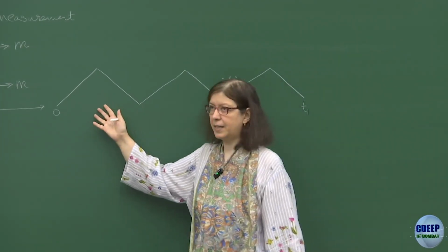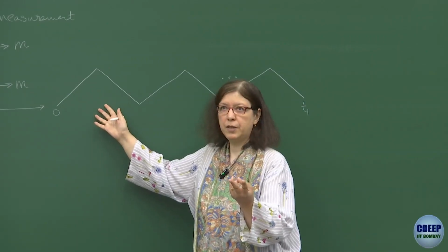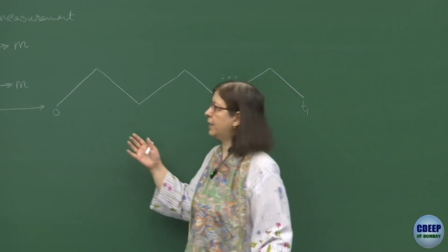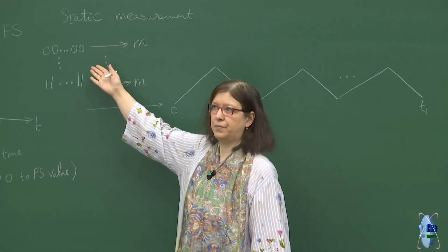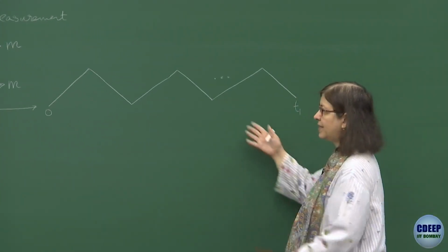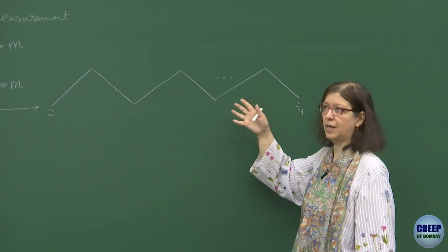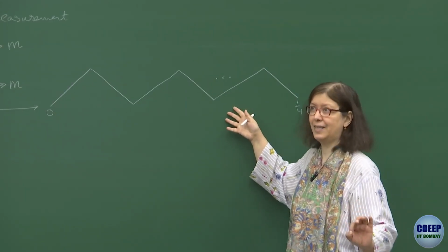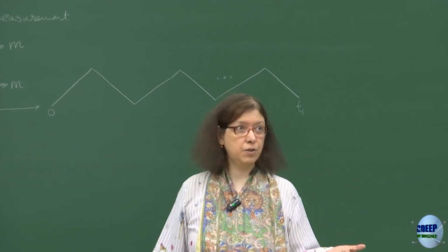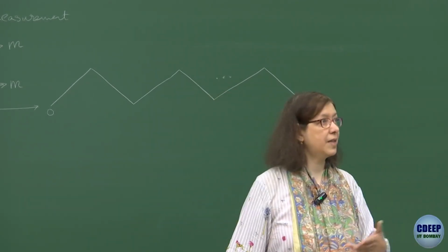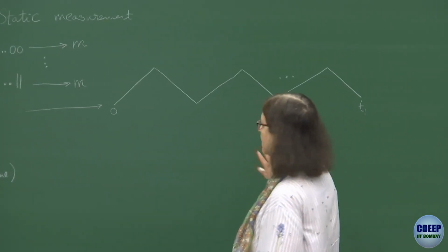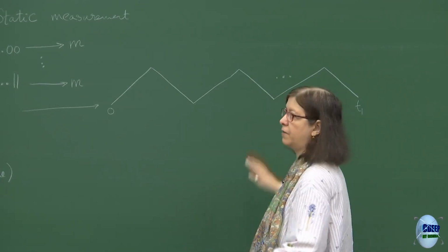Eventually, for every cycle, you have m equal to 2. Therefore, if you have, say, for example, 1000 cycles multiplied by 2, ideally you will have 2000 samples of each code. So this is the way we eventually generate the input, and this input can come from a synthesizer, can come from a very accurate DAC, and because it's low frequency, it is possible to use a very high resolution DAC, with a resolution more than even the ADC under test, and generate all these codes. Fine. So this is for the ideal ADC, ideal case, all will be equal.